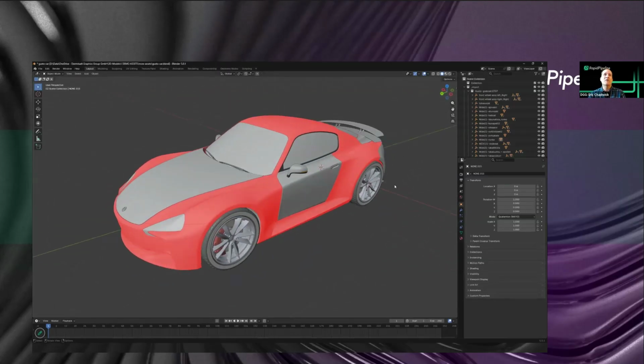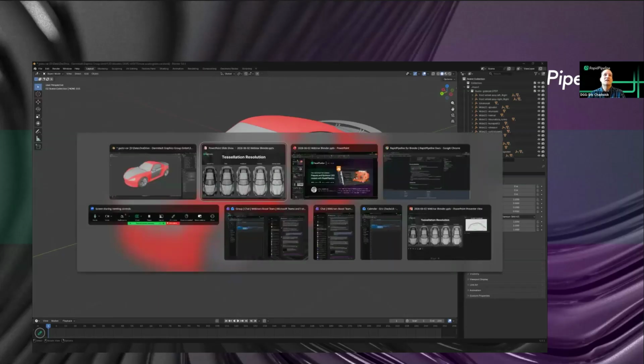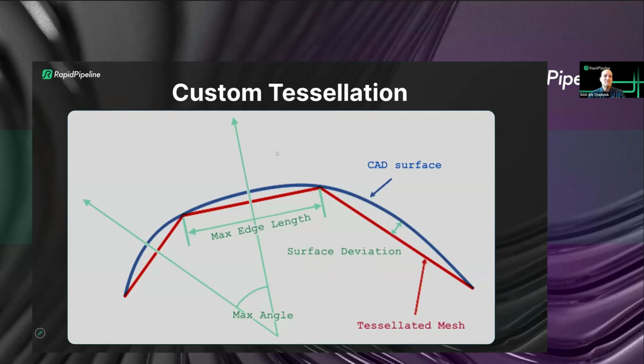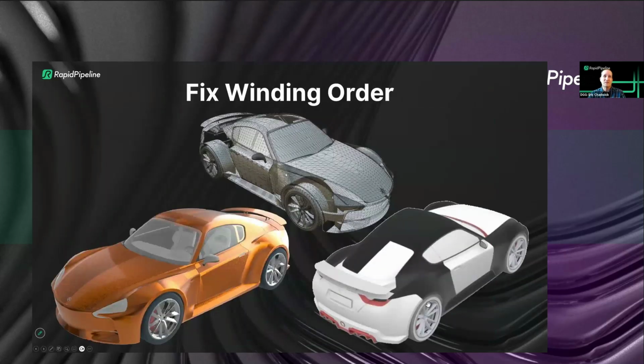And why is that important? Why do I need to flip these things? If we go back here to the slides, I can kind of show you. This is with the flipped surfaces, right? And you can see things that are inverted. If you try to render surfaces as just two-sided and just say, hey, I don't care whether they're flipped or not, some shaders are going to have problems with that because it considers the surface to be facing inwards.